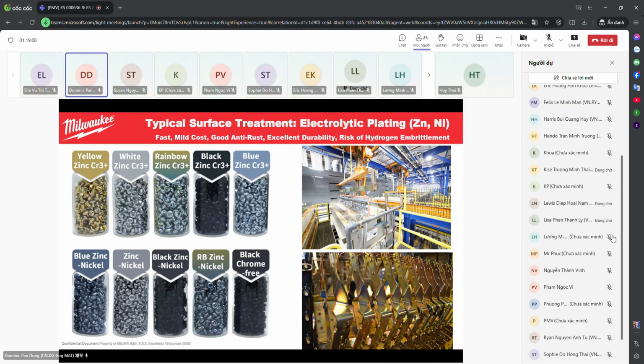surface. With some special fine tuning of the chemical additives inside the water tank, we can get different types of color, from gold to silver to blue to bluish to yellowish to black of the zinc plating layer. This is the biggest advantage of zinc plating. That means you can get various types of color you need. And it's all combined into this plating layer. You do need to add a special additive or additional coating layer so that the cost and the quality can be assured of the parts.